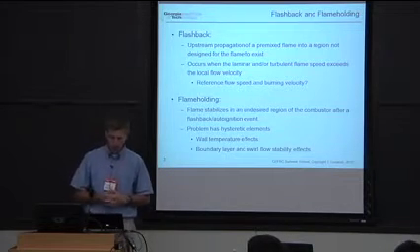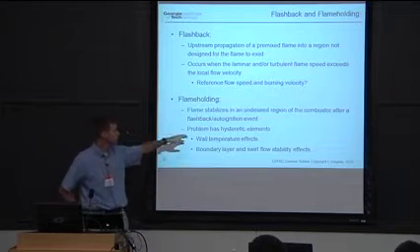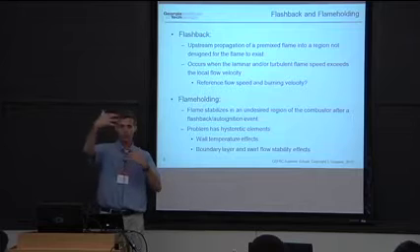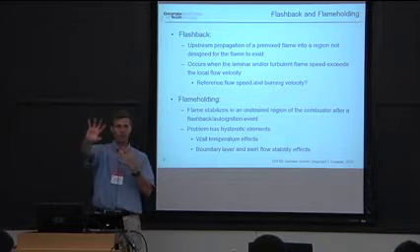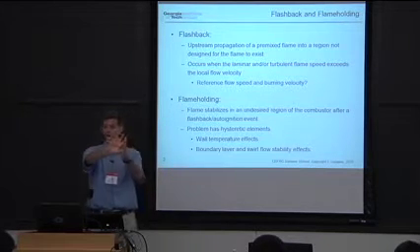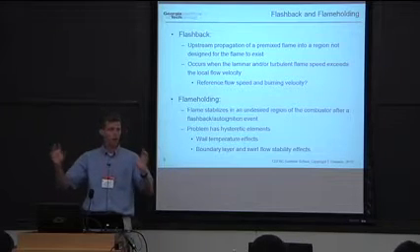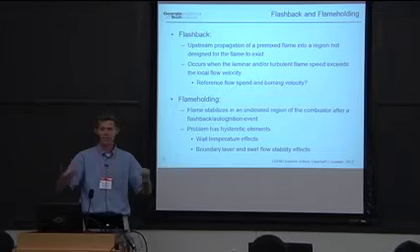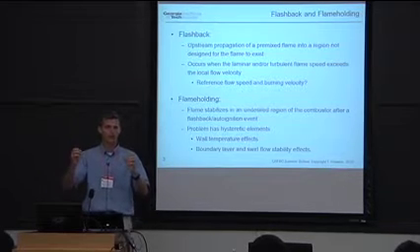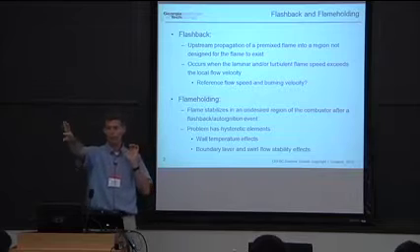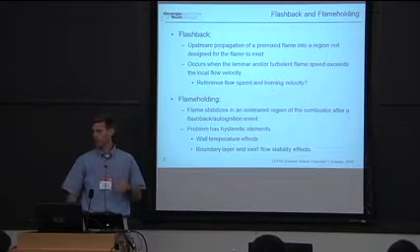And as I'm going to talk about, the problem is that there's hysteresis. A nozzle can very happily sit with the flame parked outside of the nozzle in the combustor, and the flame will not flash back. It will never flash back. But if something hiccups, something crazy happens, there's an oscillation, and the flame can come back and stay there, and it doesn't just go shooting back out when you return to your normal operating condition, that's bad.